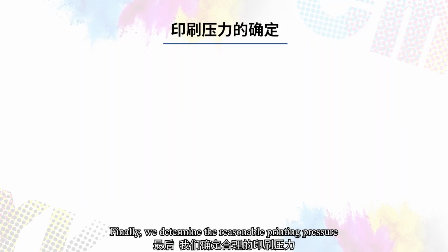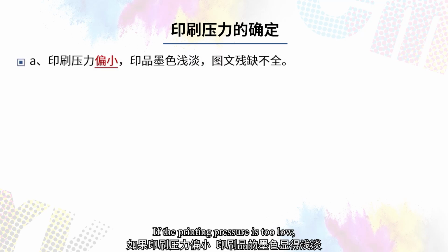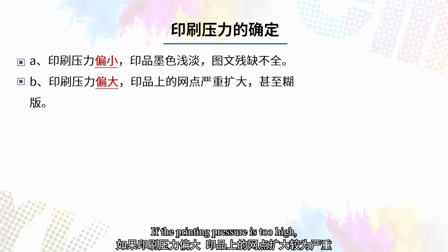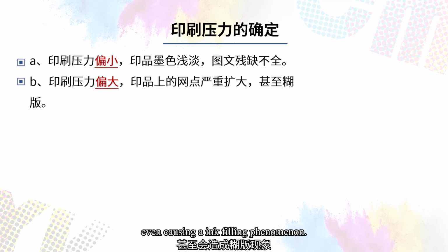Finally, we determine the reasonable printing pressure to achieve higher quality printing. If the printing pressure is too low, the ink color of the printed matter will appear pale, causing incomplete images and text. If the printing pressure is too high, the dots on the printed matter will expand significantly, even causing an ink filling phenomenon.